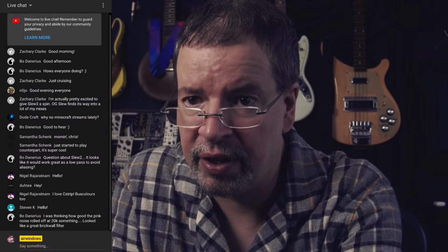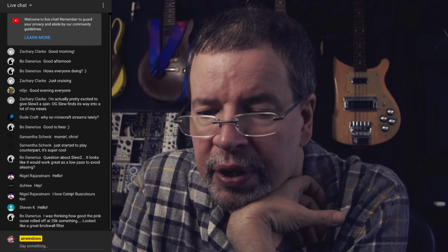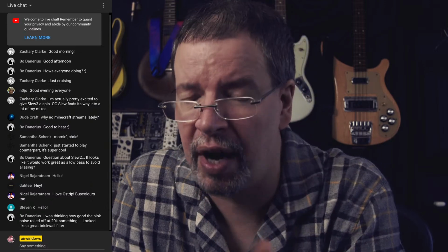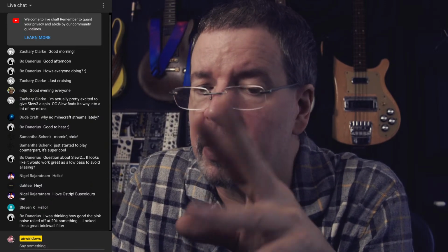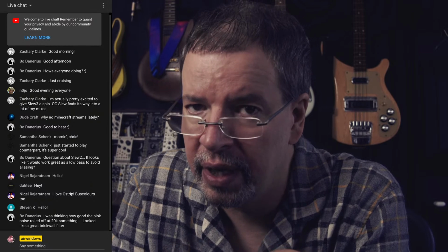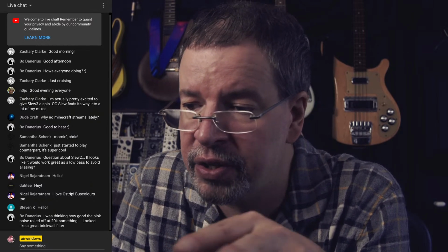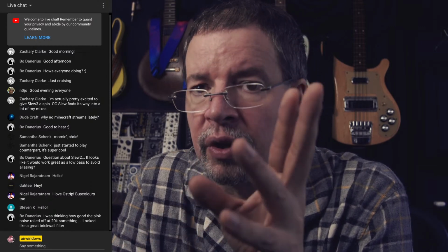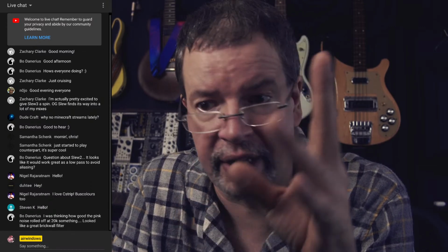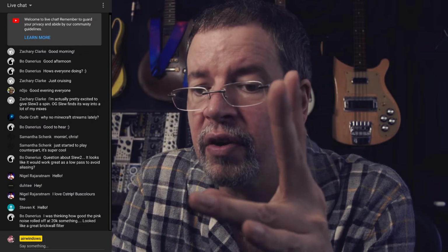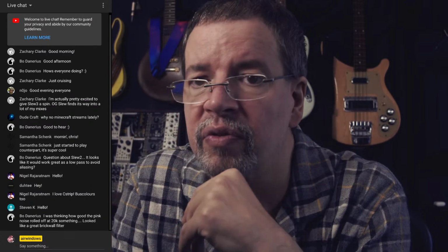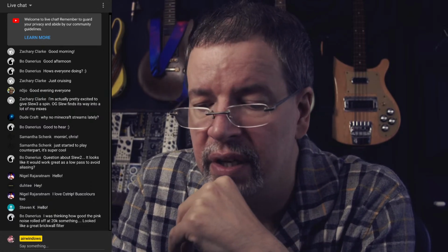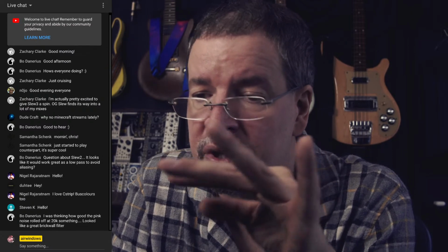And again, I'm having to divide it by 3 because simple clipping with a soft clip function is going to start generating harmonics one by one. And the first harmonic it's going to generate, if it is symmetrical, is a third harmonic. And then you push it a little farther, you get lots of third harmonic, and then you start getting fifth harmonic. You push that farther, and then you start getting seventh harmonic, and so on and so forth. They increase the harder you're clipping things, even in the smoothest soft clip that you can get,